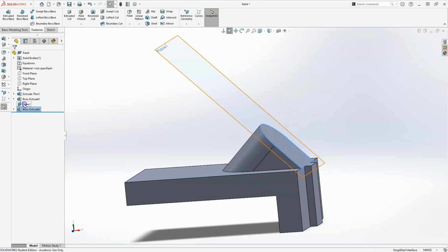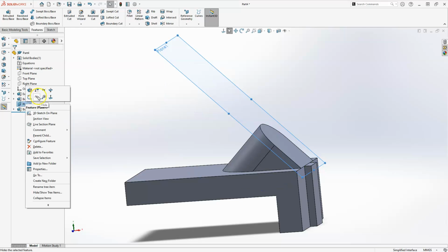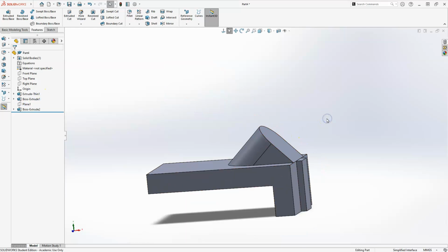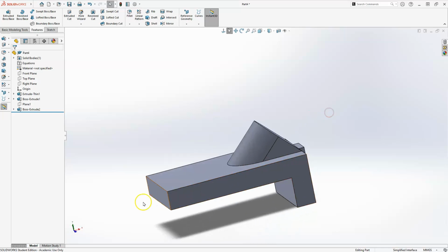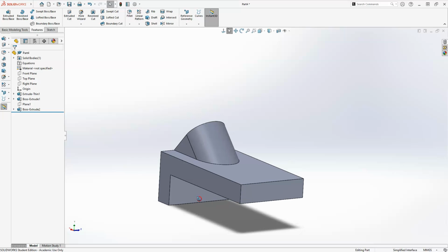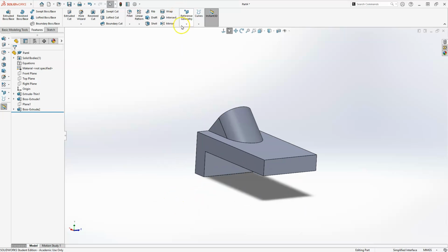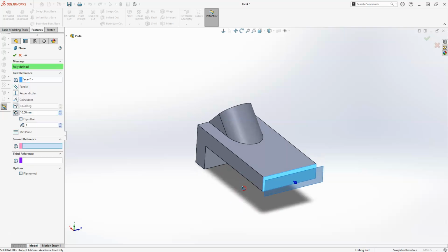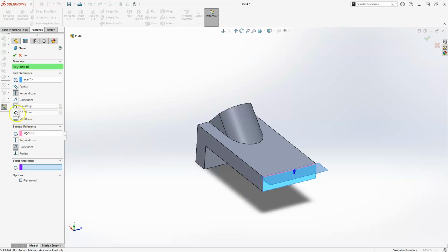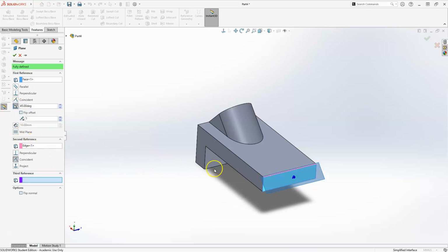Let's go ahead and hide that plane. So I'm going to select it and then I'll go ahead and hide it. All right, so now we have that front part on. Let's go ahead and do this back one. So we're going to go ahead and start off with some reference geometry again, right? So we're going to use a reference geometry of plane. And remember that this one goes 30 degrees from this face. So I can select this face if I want to, and then I can select here as my angle, right? Now I'm going to go and specify this at an angle.